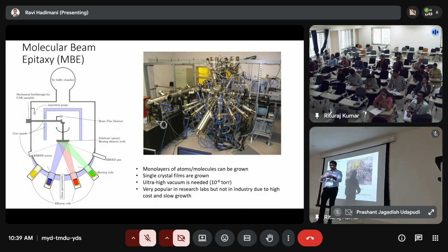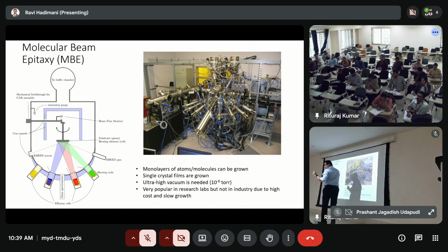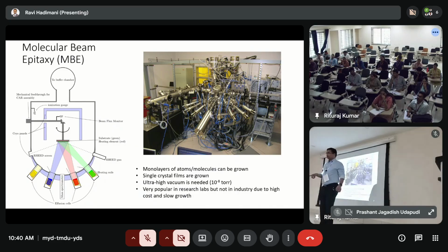So like the XRD peaks you look at, right? An XRD system is a huge, big system. You condense that to a small system, and instead of X-rays, you use electrons, and you get certain patterns when it's reflected back. That is called RHEED. And there is a RHEED in situ within the chamber to make sure that the material deposited is the material that you want.